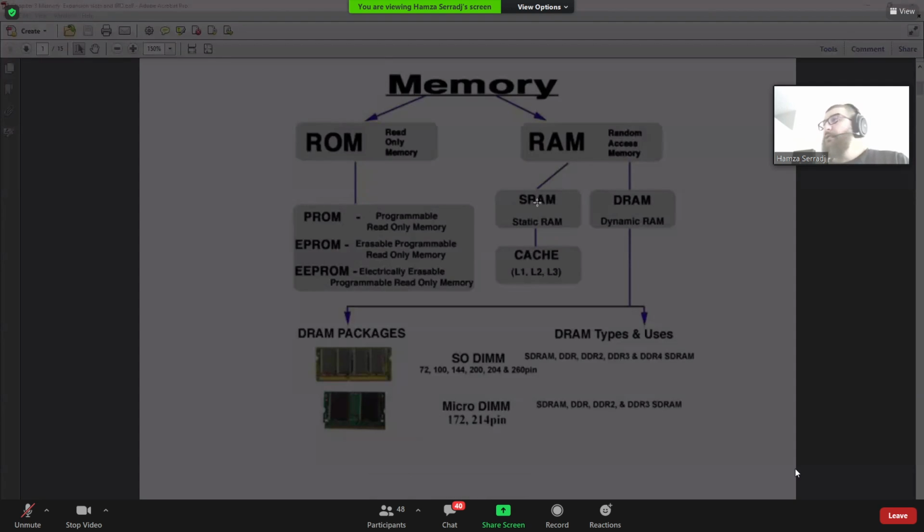Well, this one consumes less because of why? Because we need a refresh just on an instruction of read or write. So when we need to read or write, we need a refresh on the SRAM, but this one needs continuous refresh, even if we are doing nothing in there. So just keeping the data inside, we need that electrical refresh. So this one is more consuming than the SRAM. The DRAM is much more consuming than the SRAM on electricity.